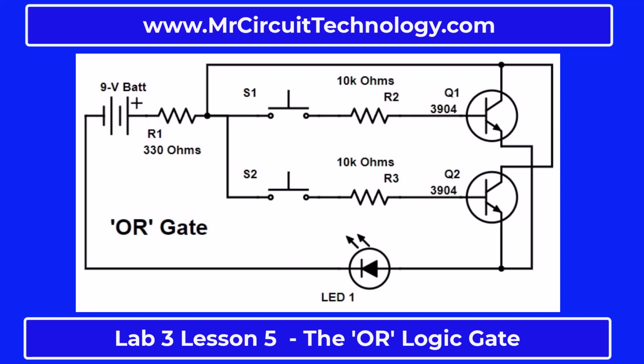If you do not press any switch, the LED will not light up, which indicates a false on the output of the circuit. So as you can see from this explanation, this circuit works like an OR digital logic gate. When either input is true, the output will be true. That is to say, when you put a voltage on the input of either transistor or both transistors simultaneously, the LED will light up, indicating a true on the output.